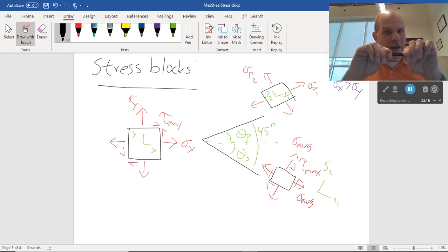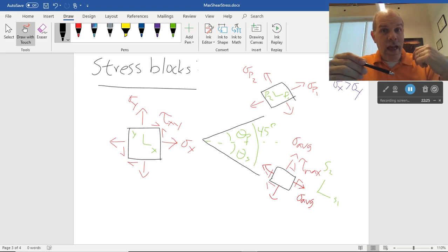I have no axial stress there in the x or y direction if I'm just twisting it. Therefore, sigma x and sigma y, so to speak, are equal. I know then that I'm looking at the maximum shear stress. If axial stresses are equal, you've already got the maximum shear stress. Just like if your shear stress is 0, you've already got the principal stresses. That's the way you can tell when you have the maximum shear stress.